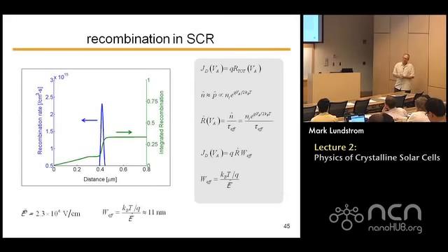But in these bimolecular processes, when you do radiative recombination, you do get np, and what that means is that the tau is dependent on the other quantity. I would write it as n over tau, but the tau would have a 1 over p dependence in it. It would be dependent on the carrier density.